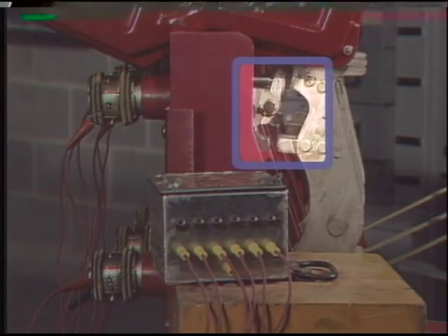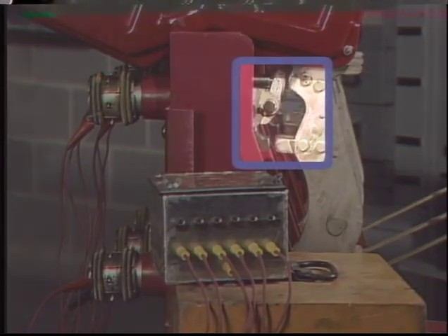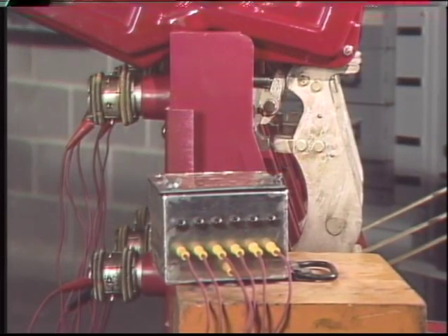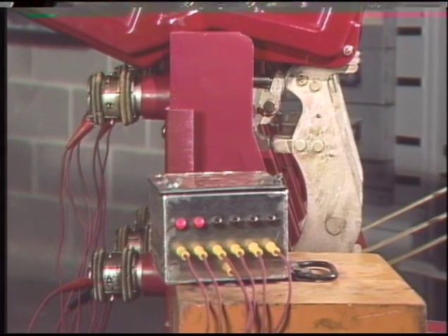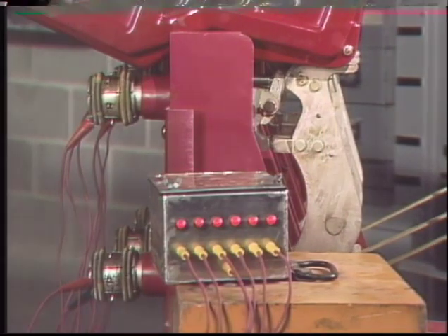After a breaker has been cleaned and inspected, the contact adjustments can be checked. We'll look at contact adjustments in detail later, but in general, there are 3 basic contact adjustment checks. One of these is initial contact engagement, which means that when the breaker is closing, the arcing contacts should touch at about the same time.